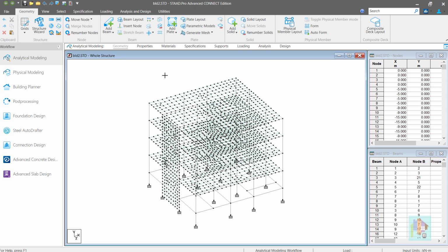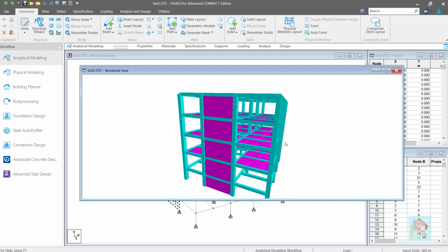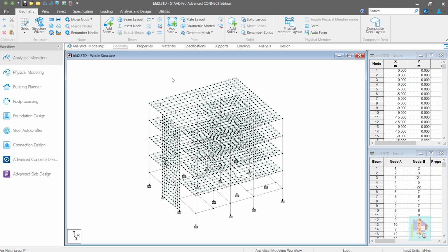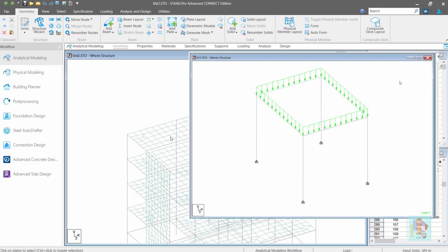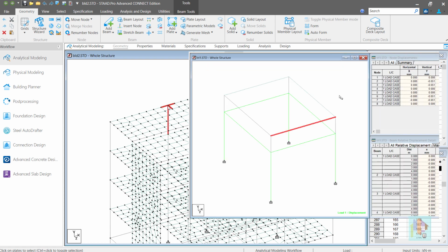Another very common example is plate modeling, whether that is a floor slab which we want to model using plate elements, or a mat foundation or shear wall. In analytical modeler, we can generate a slab or wall using finite element meshing. When we model a plate mesh, all the connecting members are subdivided in smaller segments, which we call analytical members. It is not possible to create a single plate element for the entire slab, as that will not replicate a realistic condition, where the slab is connected at the corner columns only and there is no connection with the beams or interior columns.